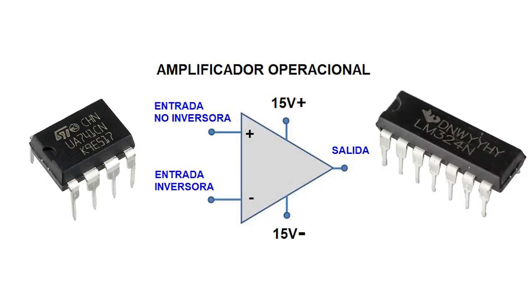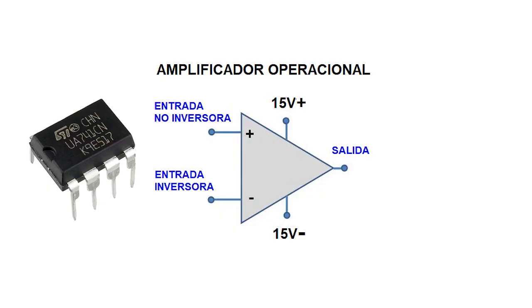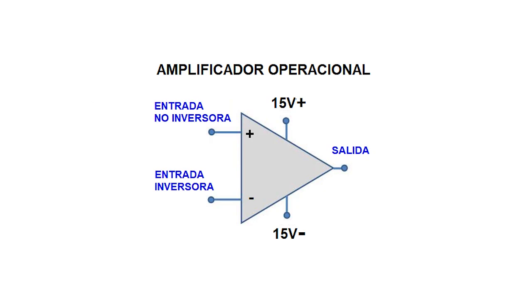In the image we see the schematic of an operational amplifier. We have 5 terminals. Connection to our power supply we can do with a single supply or with a symmetrical or dual supply. With respect to ground, we can have 5, 9, 12, 24 volts, maximum 30 volts. This is if we feed it with a single supply. If we feed it with a symmetrical supply, we can have 5 and 5, 9 and 9, 12 and 12, and 24 and 24.